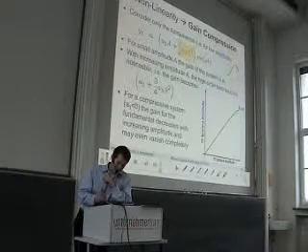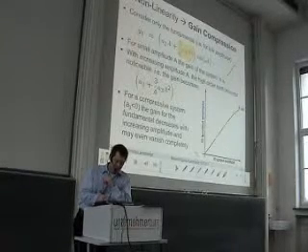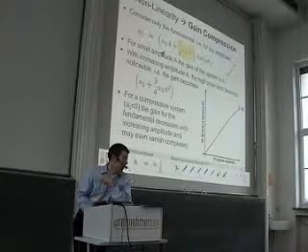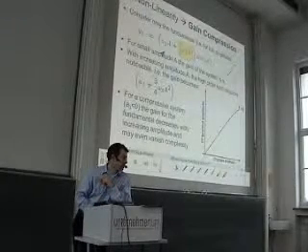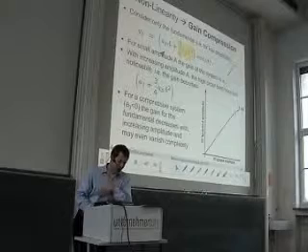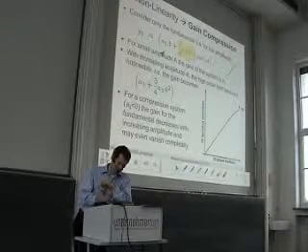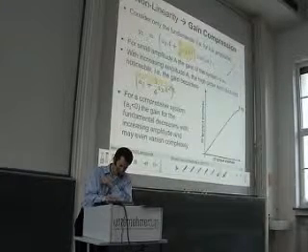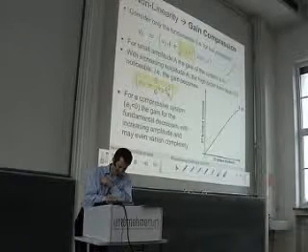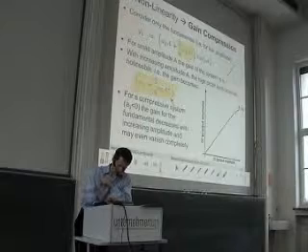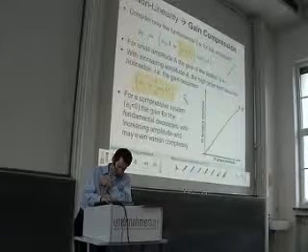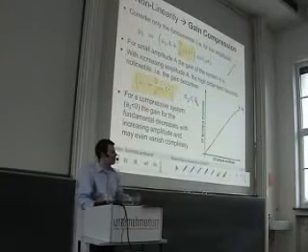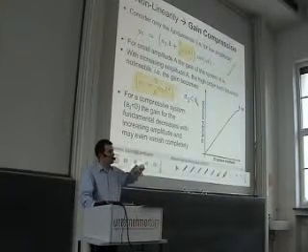So this actually is the gain of our nonlinear system. I have to put the capital A out, then I end up with the gain here. So this is the gain of the nonlinear system. a3 is negative, so we can say a3 is smaller than 0. But then you see, if the amplitude goes up, the gain goes down.